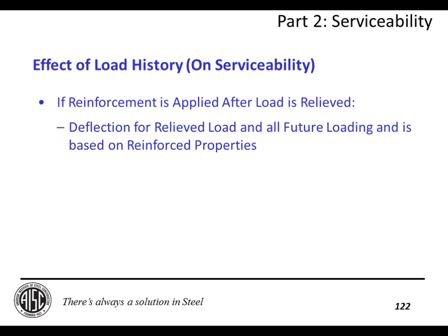If you want to add reinforcement after the load is relieved, then you get that composite property, that fully reinforced moment of inertia, to be active for all of the load. So whatever load you removed with jacking plus any future load.